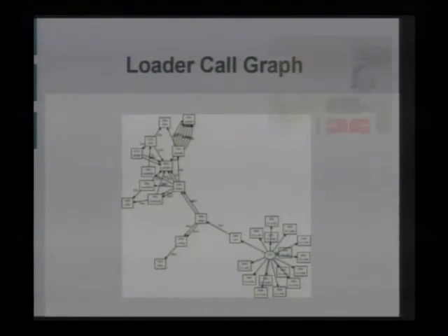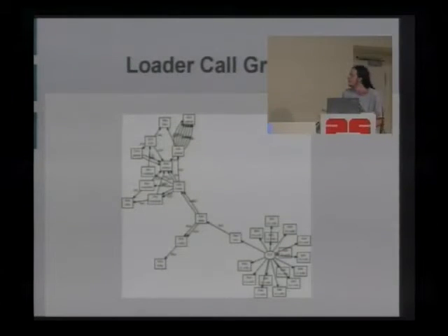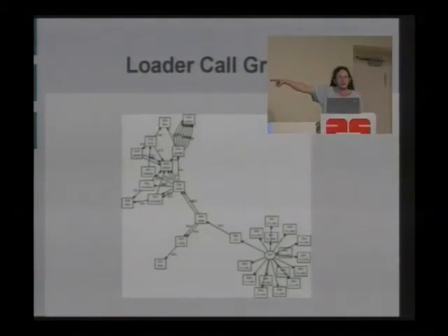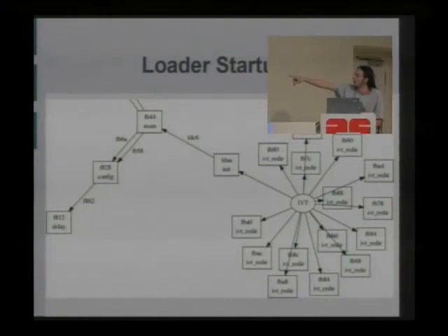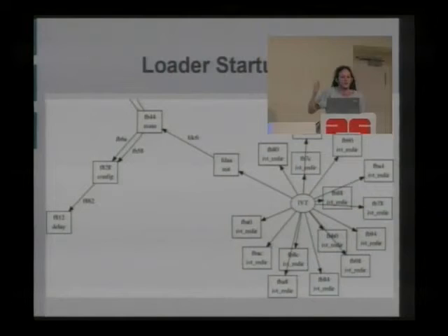And those will handle things such as an incoming serial byte. And you'll note that only one of them actually calls another function. And that is too small to read, but that's init. Okay, so then init calls main, which calls configure, and these names had to be written by hand after the code was reverse engineered. But only one of the interrupts actually calls anything, and that is the interrupt that is executed when the chip is turned on.